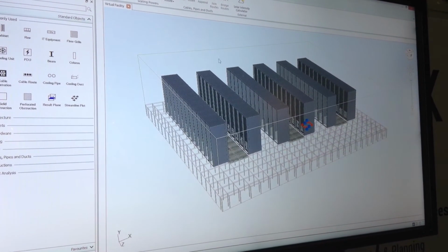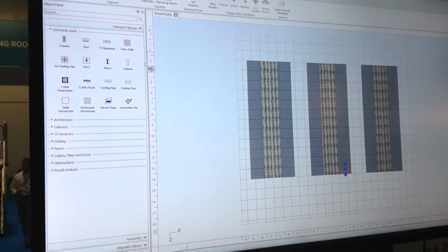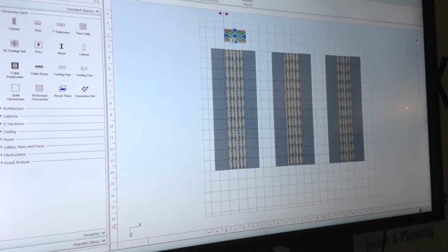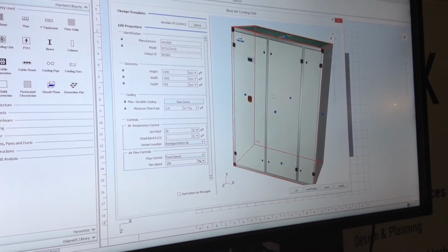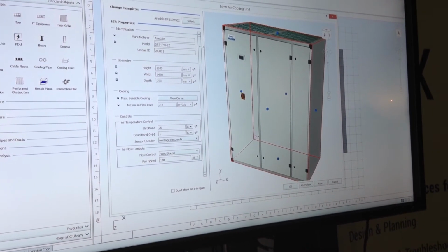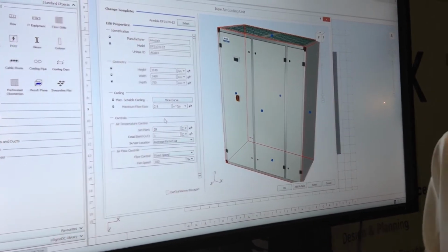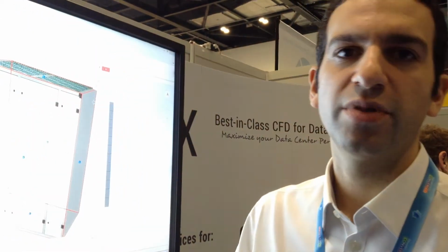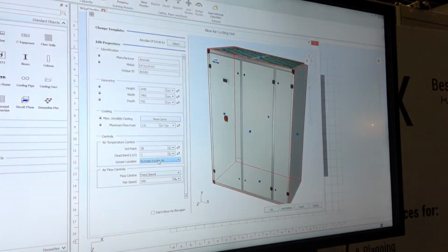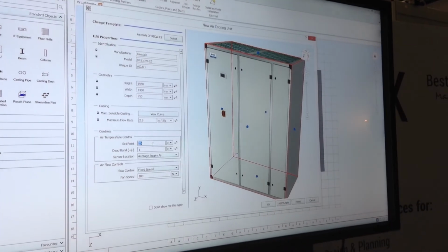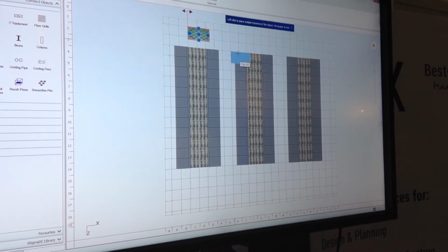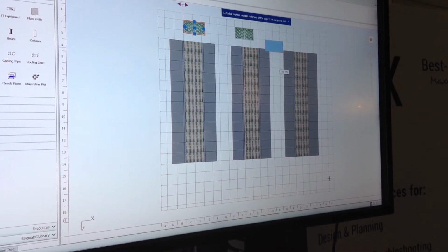At this point we'll just add some cooling. So again I'm going to drag in my cooling ACUs, and at this point I've just got an AirDL unit, and I get some basic controls. If I want to do supply control, return control, VFDs, any sort of complex pressure control, you can set all that up very simply and easily in the software. For now I'm just going to say, let's supply it at 22 degrees, let's try and push our data center, and I want to add, let's go with 4 of these.